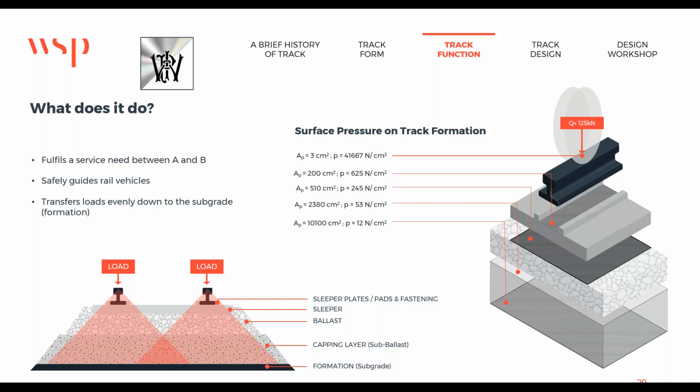The formation below the track needs a crossfall, like a road camber, to allow water to run off to the drainage system or to the embankment slopes or longitudinally along the track sides. In cuttings, the ingress of water, as runoff from external surfaces or from higher water tables, is often intercepted before it reaches track level. And in fact, track drainage systems quite often are not actually draining the track. They're preventing the water that's presented to the track from a third party, a farmer's field, for example, from getting into the track and making it waterlogged.